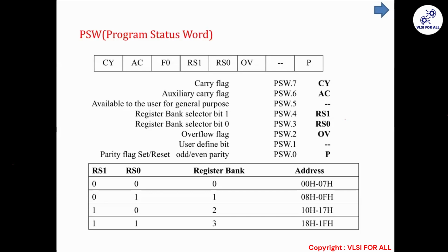I am adding at my level. Starting from LSB, LSB will give me 0. Then 0, 1 plus 1 is 1, 0. So 0, 1 carry. 1 plus 1 plus 1 is 1, 1. So 1 and 1 carry. 0 plus 1 is 1. 0 plus 0 is 0. 0 plus 0 is 0. 1 plus 1 is 1, 0. So 0 and 1 is carry. So what 8-bit I am getting is 0, 0, 0, 1 and 1, 0, 0, 0.